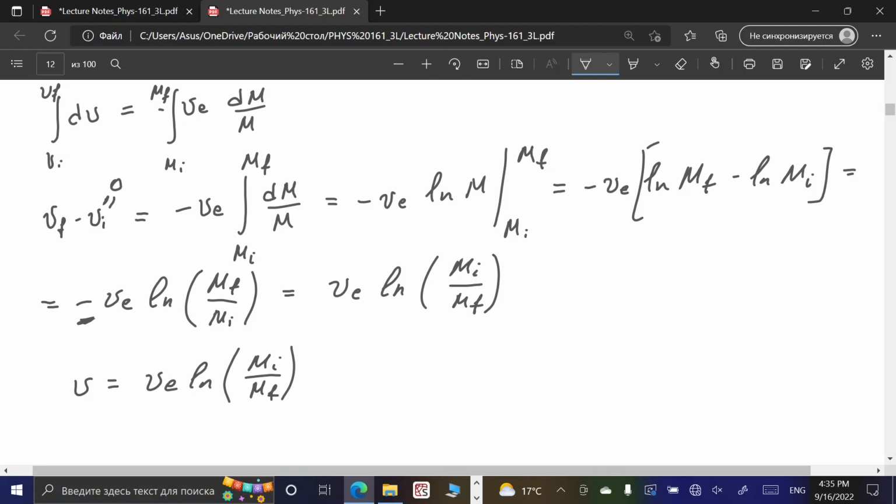So development of new types of fuels which generate more heat per burning unit of mass of this fuel. And also we need to develop quite efficient oxidizer, because keep in mind that rockets are traveling in the space. They do not use air as a source of oxygen, and even this short time when they travel in atmosphere, the amount of oxygen which can be provided from air is limited. So you need to have a combination of fuel with oxidizer. So it's either solid fuel rocket engine or liquid fuel rocket engine. In both cases, we have a combination of fuel itself and oxidizer.